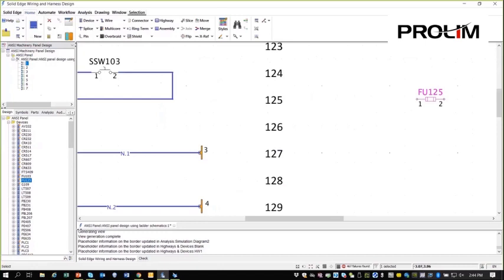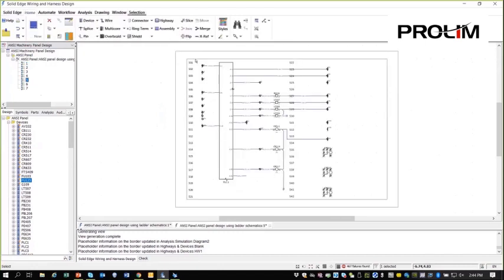So likewise, when we go to sheet 5, open that up, again, we get the same numbering, but everything begins at 501 on up. So this is supported in the symbols library where you create these ANSI standard drawing sheets that you need for your ladder diagram. So I wanted to make sure that I covered that as well.